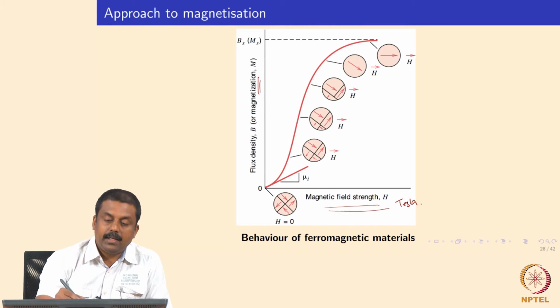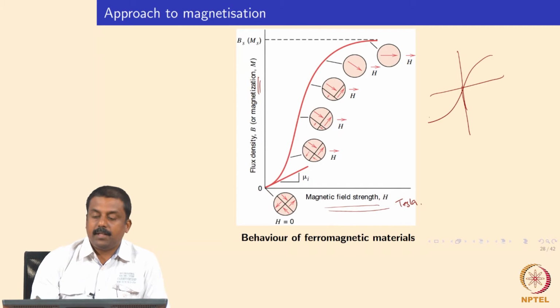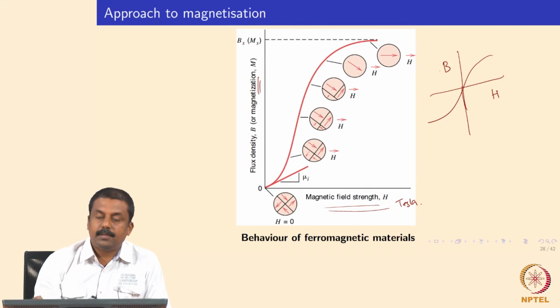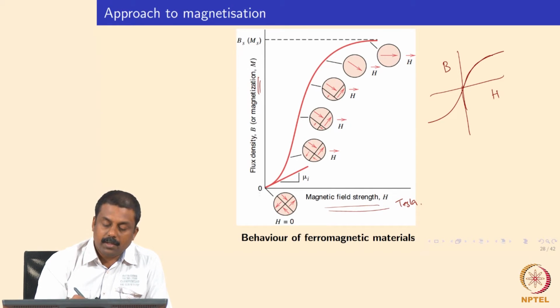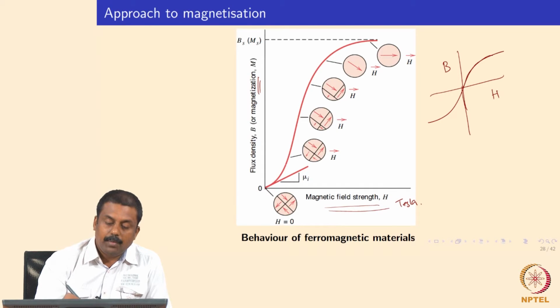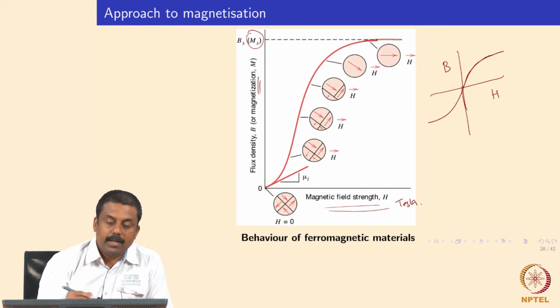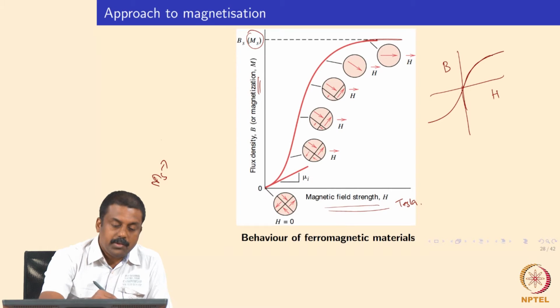So we have a typical magnetic hysteresis curve we must have studied in +2 physics. We generate such a magnetic hysteresis curve, and typically when you start applying a magnetic field, the ferromagnetic material gets magnetized as a function of the applied field, and then upon reaching a critical field strength, the magnetization saturates to a value, and this saturation value is known as magnetic saturation, MS, or saturation magnetization.